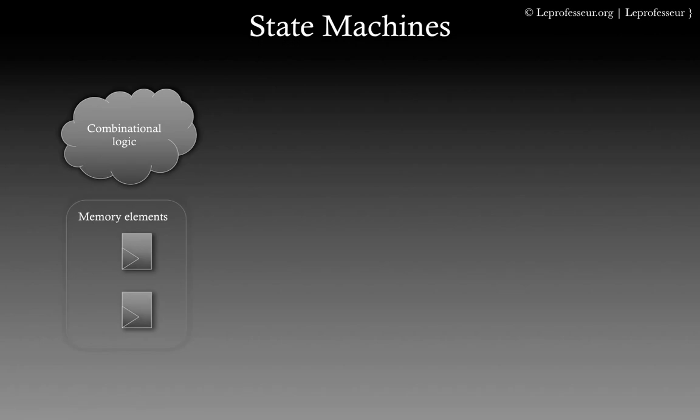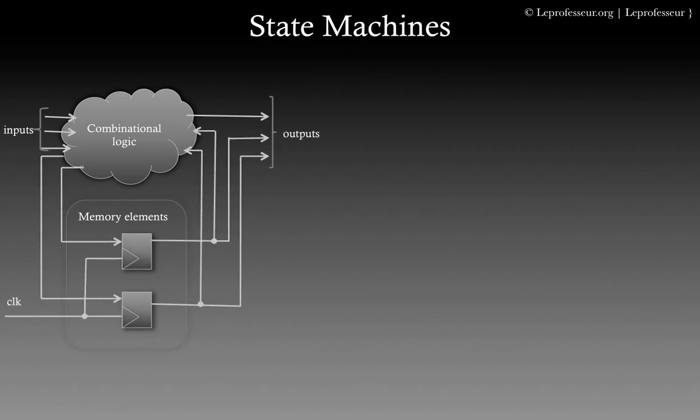Basically, it's the combination of the two. The combinatorial logic part is doing the job of input encoding, or say state machine encoding, for the state in which your circuit is, and also decoding for the output, right? So we have certain inputs and certain outputs, and those are connected.